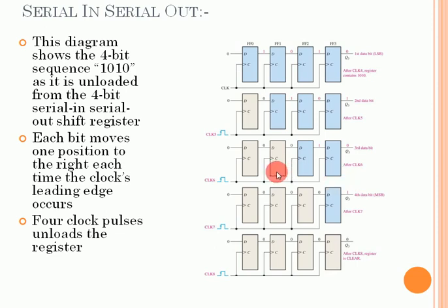Now you can have the output 0 and 1 here, and the next 1 and 0 are shifted to the next flip-flops. Now at clock 7, those flip-flops are empty, and data is being shifted to the right hand side.